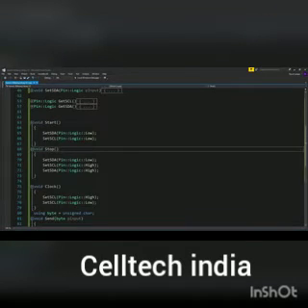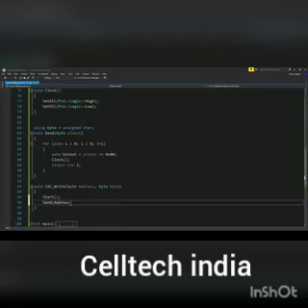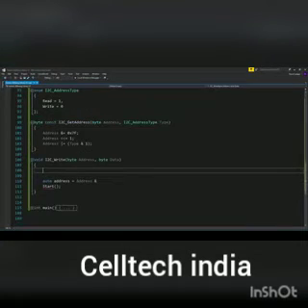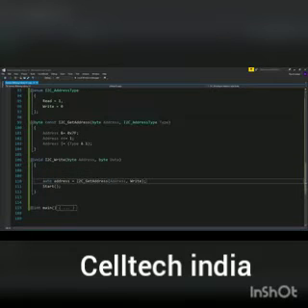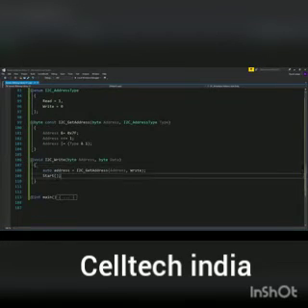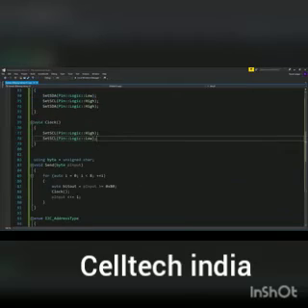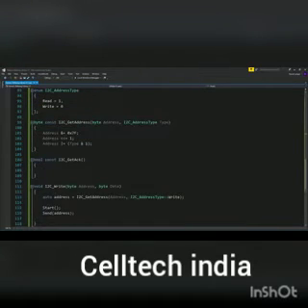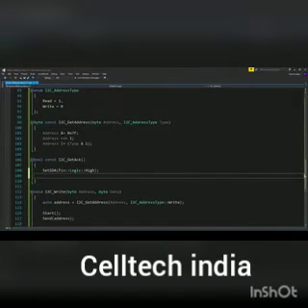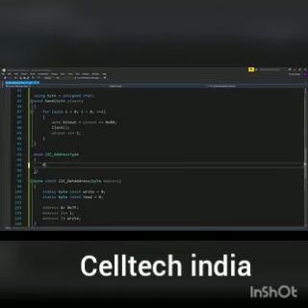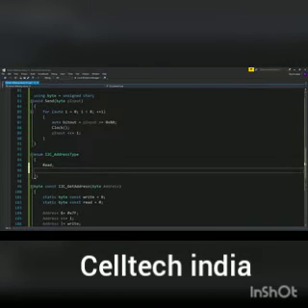Okay, so we need a start and a stop function, and those just assert the start and the stop conditions we talked about before. Those are going to be used in the I2C write, and the first thing we're going to do in that function is assert the start condition. Then we're going to send the address, of course, and then the data, and then we're going to assert the stop condition. In between each of the blocks of data we send, we're going to look for an acknowledgement.